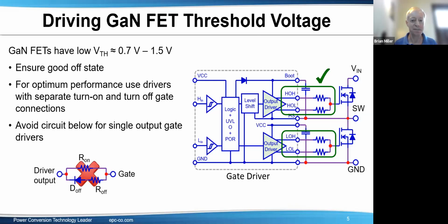Okay. Next question is, can we use ferrite beads for R on to limit the ringing effect in the gate loop for GaN switch? It's probably best not to. We think it's not good. I know what you mean. There's a lot of MOSFETs that have that, and there might even be some other GaN suppliers that think that's okay.